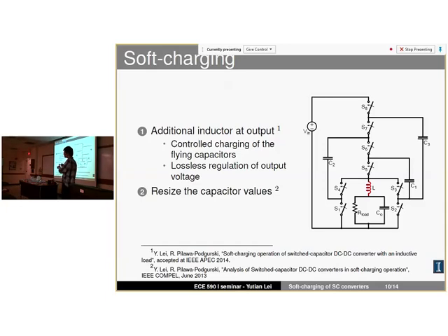So with that actual converter, the buck converter has to run at a higher frequency to look like a constant current source to the switch capacitor. So you added two switches, and they are switching at high frequency. So there's some penalty on efficiency already.